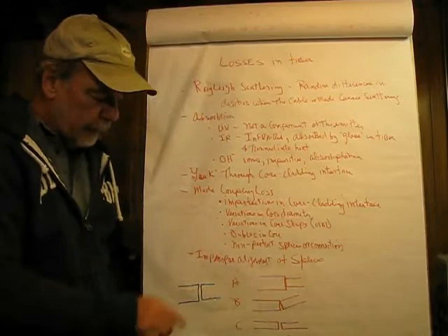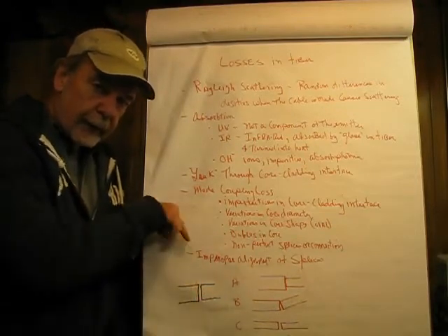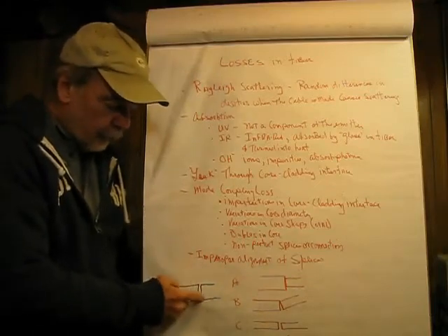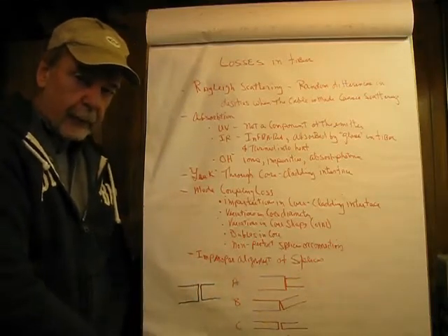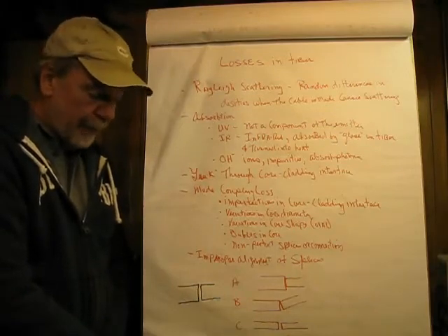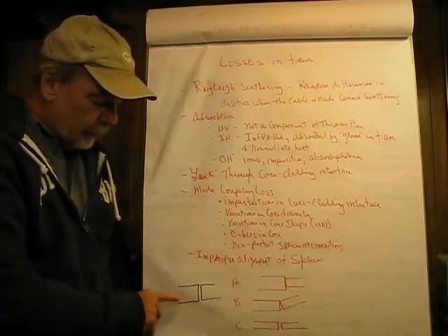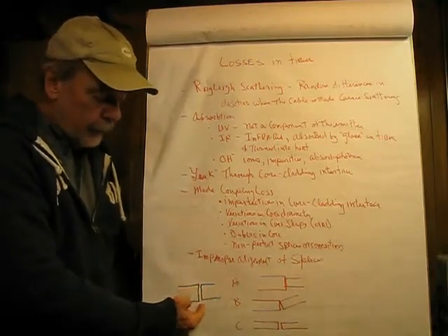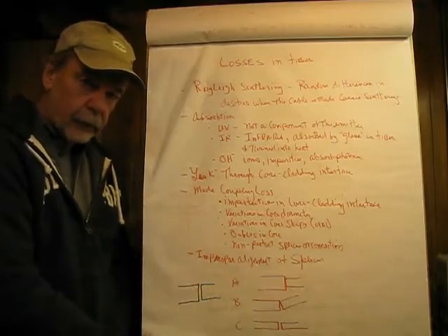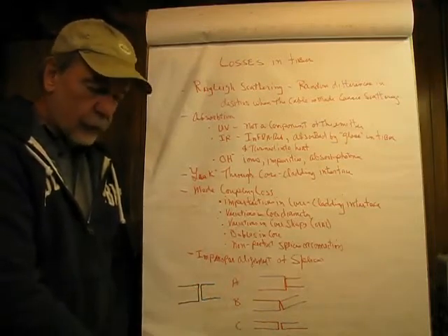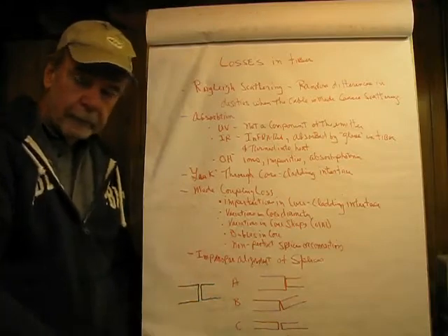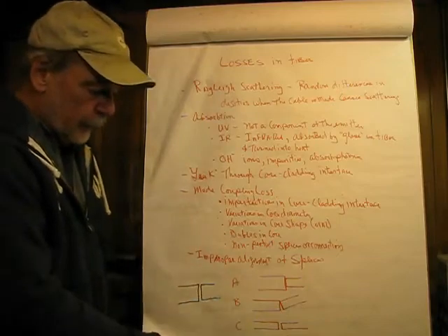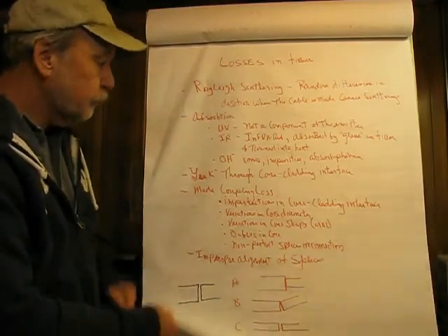Line it up correctly. Then they flip the mirrors to look at it 90 degrees to make sure it's not off in that dimension. And when you flip the mirrors back and forth and it looks like this, then they basically melt it together. Then, kind of hard to believe this, they inject light here and measure it here without cutting it. And they can determine the loss of the fuse, of the connection. And if the loss is too high, cut, do it again. So we typically see maybe 0.6 or 0.7 of a dB in a splice, sometimes less than that.